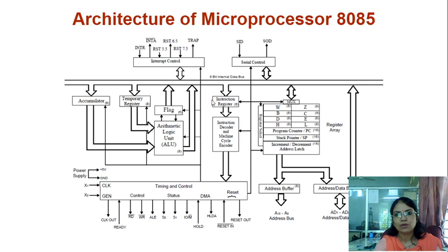Now going to this block, that is the instruction register and instruction decoder. Instruction register, here it says register, means nothing but it is also one of the storage. This block is also used for the storage purpose, and again the number is written as 8, means here we are storing 8 bits of content. But this program counter, instruction register and instruction decoder have a proper chain for the execution of instruction.